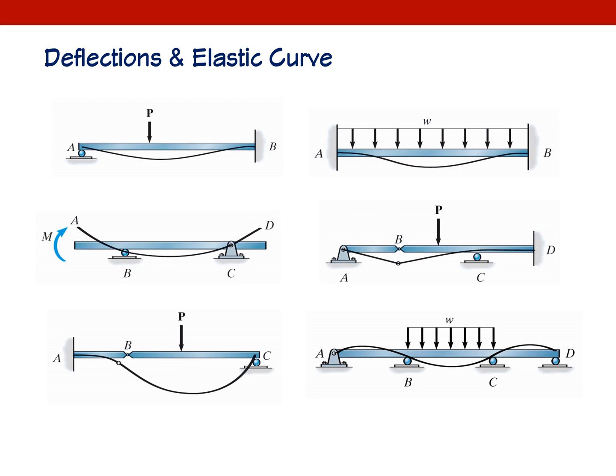Okay, this is a typical elastic curve of the beam, and please memorize several deflected shapes, which are elastic curves. Here we have a deflection angle. Here we do not have a deflection angle, which is 0. And all other shapes are there, and you may want to draw them several times so that you can memorize. It will help a lot, and it will help prevent any possible mistake in applying the analytical method.